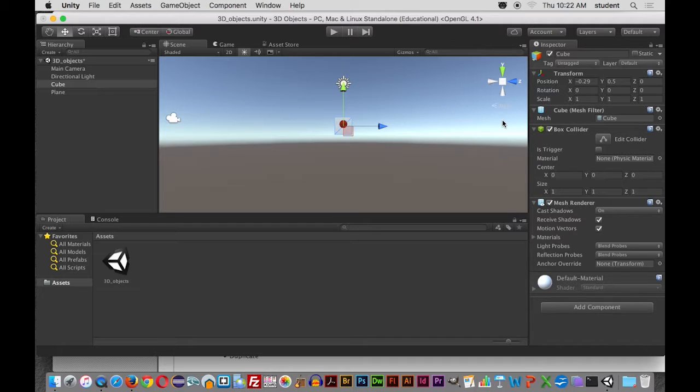And notice, by the way, when we look at the right view, that the plane seems to have disappeared. So on the Gizmo right here, in terms of navigating through our system, where it says perspective, I'm going to put my cursor, right mouse click on that, and select right.